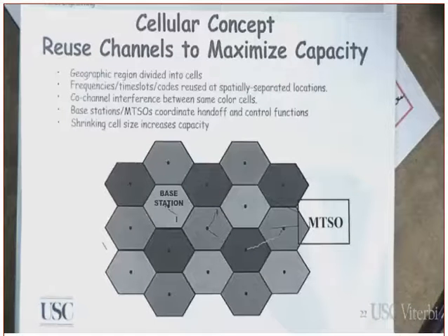Always keep in mind, by the way, even the frequency can change if there is a relative motion between the transmitter and the receiver. Clear? What do we call this? That's the Doppler effect. That will even make the channel even worse. Are you following on it? The idea of how to calculate all of these is what is known as a delay spread. A delay spread means what? What is the maximum delay encountered by a signal? Same signal. Remember, you are going to receive multiple versions.